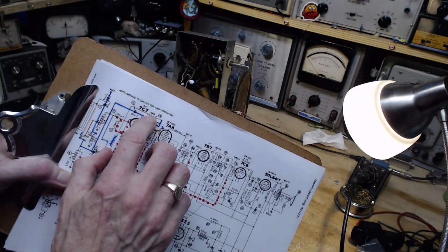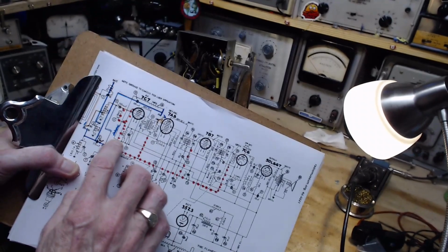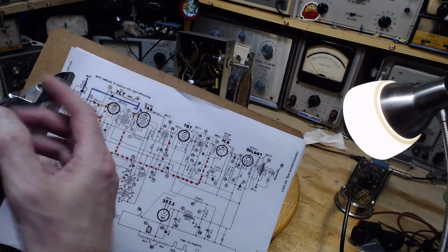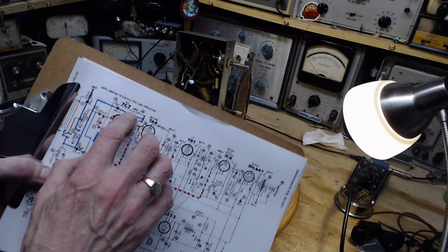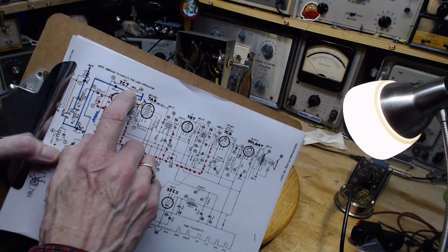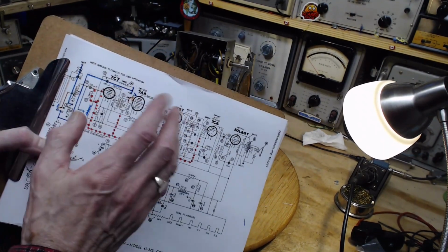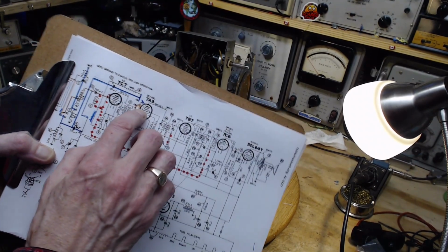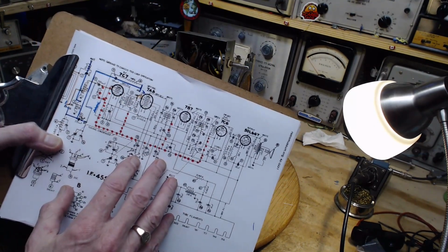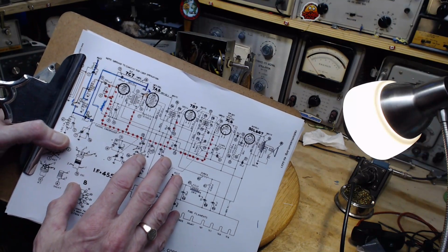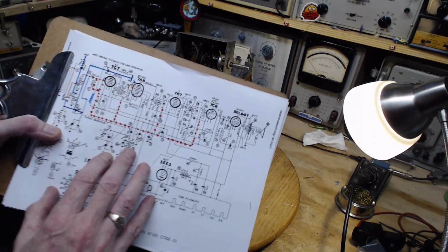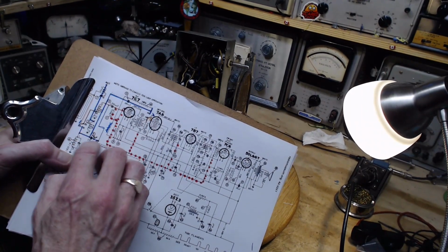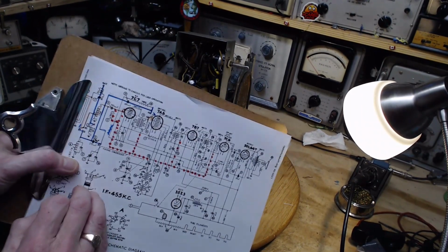Okay, so the resistor and this wire goes back to B minus along here. I forgot the proper term for it. It's the resistor that's going to bleed away any charge that might build on the grid otherwise. And the bias for this tube, it must be kind of self-biasing. Not sure about that, but how else can it be biased? So that's the situation. It is this weird circuitous thing going on.